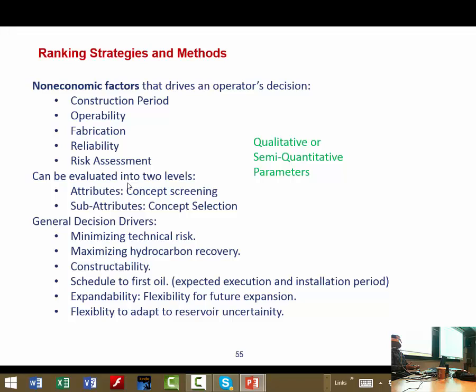But in the North Sea, you don't. This is not mandatory, it is optional. But when you have a disconnectable turret, then you have a limited size for the number of risers. So if you want to use this concept, an FPSO with a disconnectable turret, with a very uncertain field, then you may have a big risk here.